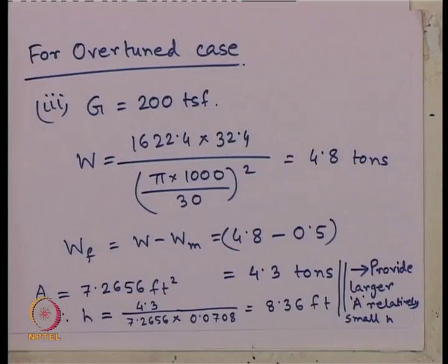And another practical implication, when we are providing the sizes of these foundations, we have to be careful that we generally provide in terms of workable dimensions. What are workable dimensions? In terms of generally in multiples of 25 mm, isn't it?